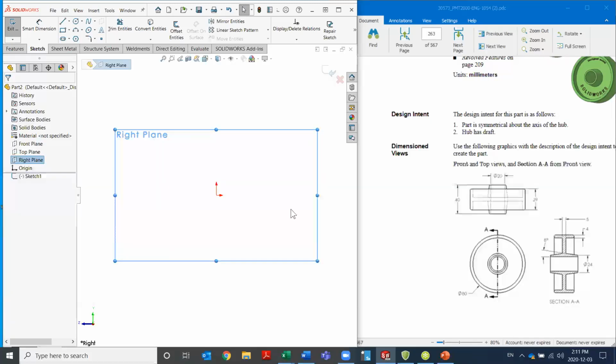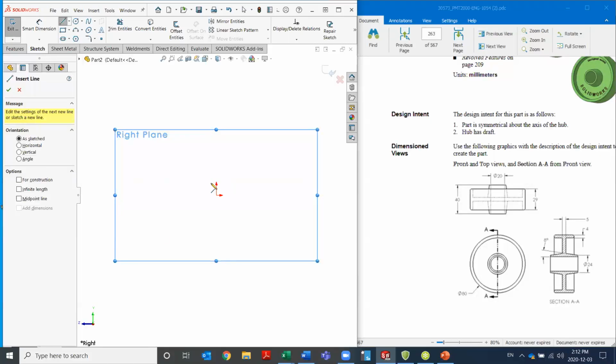what I'm going to do is create those axes in here, and I'm going to do that just with a construction line. And we do like to introduce shortcuts. Again, these are just going to make your life a lot easier as you get more proficient with the program. So things like when you're going to start a line, you might just hit the L on the keyboard and it'll jump you right into the line tool. And then we might say, okay, we want axes going across here. Those are going to be construction lines, and I want them to go across but attached to the origin.